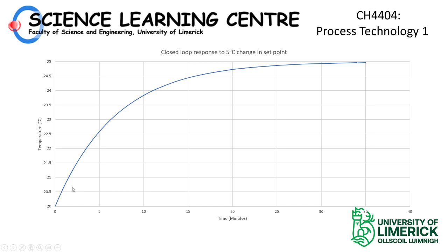But now in this curve, we reach there way faster. So after 7 minutes, 7 minutes would be right around here, and we would be covering 63% of the temperature difference, because that's the definition of time constant. And within a time period of 30 minutes, we would be very close to our steady state temperature. 35 minutes is basically 5 tau, and we're getting very close to the final temperature.